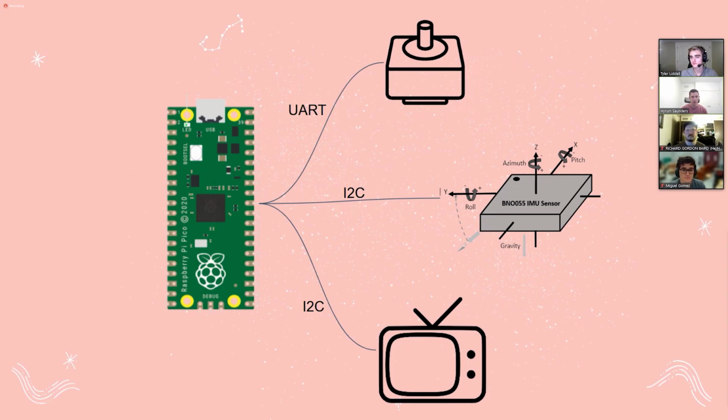The Pico is using UART to communicate with our TMC2209 motor drivers, and the TMC2209s have a really nice interface, so we don't have to send pulses to the motor if we don't want to. We can just write a speed to a register, and the chip does the rest for us. We did actually end up sending pulses as well, though, for finer motor control.